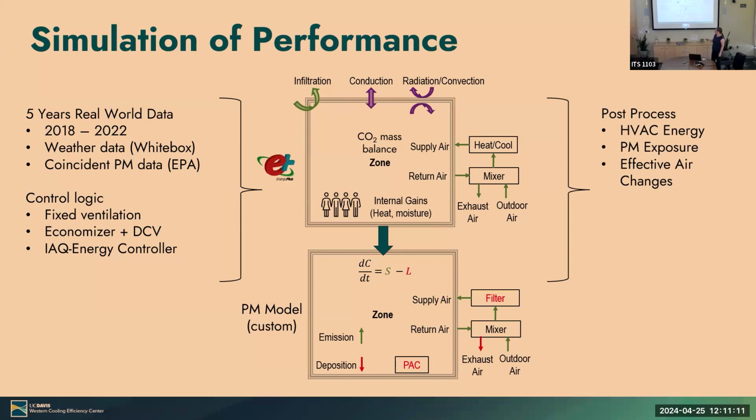But the point is, in order to run an energy simulation, you have to know something about the weather. You have to have a weather year file that you're simulating your building in, right? The building has to be somewhere, it has to have a weather file. What's really tricky is that to simulate the particulate matter, you have to have a particulate matter file. Well, people have spent decades building typical weather years, but there's no typical particulate matter data anywhere.